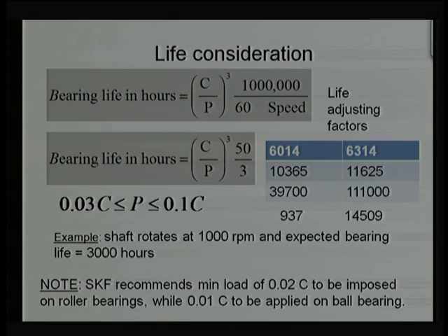There is another consideration: this bearing life has been estimated without correction factors, what we call the life adjusting factors. We assume here bearing life for 90% reliability. If we require other than 90% reliability, that factor should come over here.